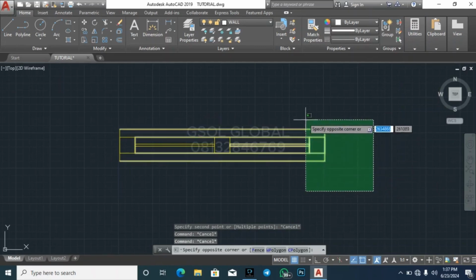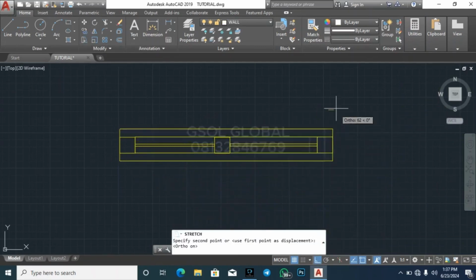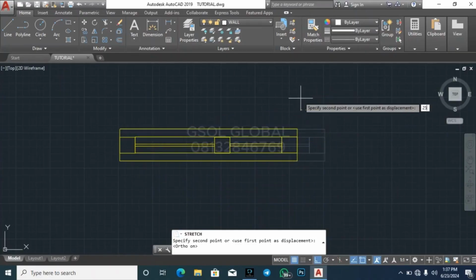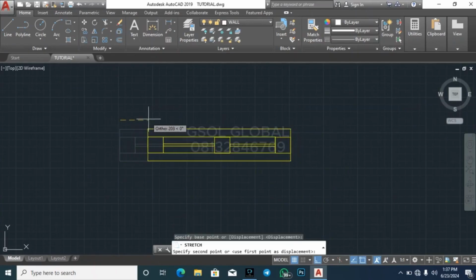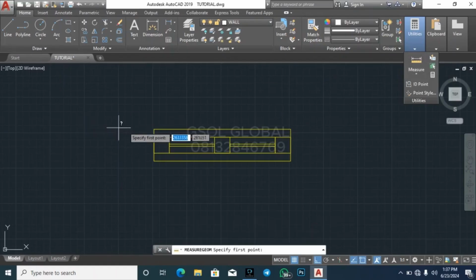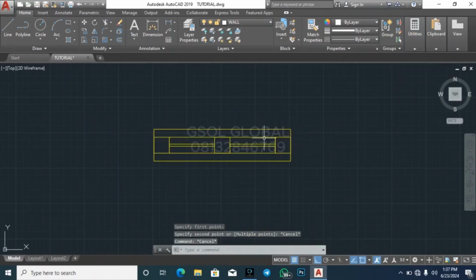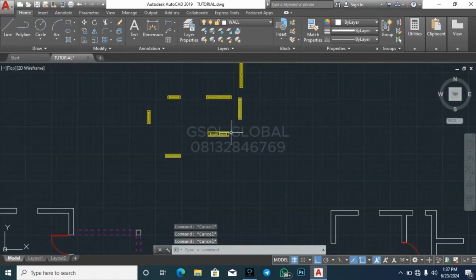So let's go ahead and reduce 250 from this point. That's 250 from this first edge, and then click to that edge, stretch it inside 250, and now you will have your 1 meter, right? Good. So this is it, and we have our 2 to 5 width intact.